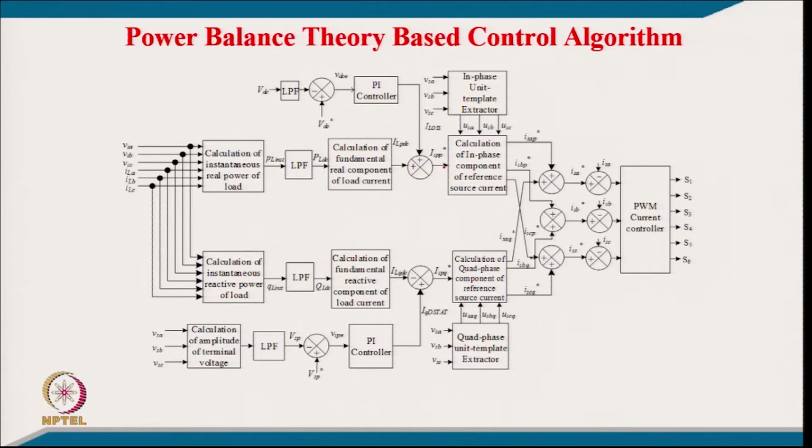You can call it that, and certainly from the supply voltage we calculate the in-phase template, and this amplitude is multiplied with the template. So, we get the active component of current, or the in-phase component of the supply current. Similarly, this is for the active phase component of current.